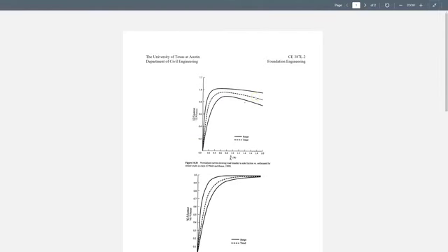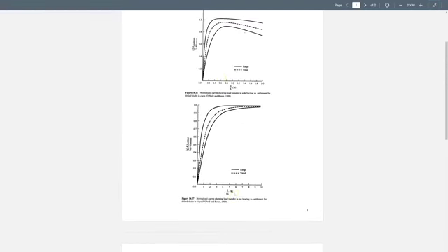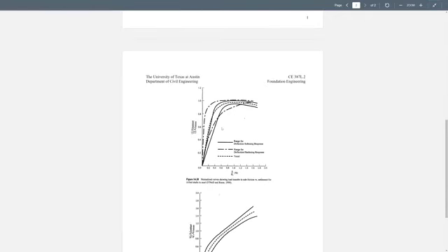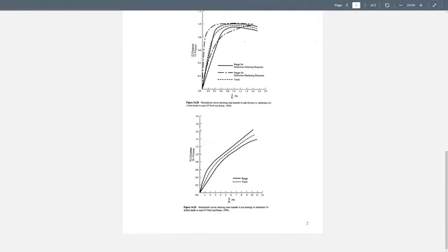So that represents your TZ curve. Likewise, this is the QZ curve. This is based on drilled shafts in clay, and these are strongly dictated by the type of foundation. Those are the drilled shafts, and this is also the drilled shaft curve for sand. If you have piles, then you have a different kind of curve. So this is only for the drilled shaft.